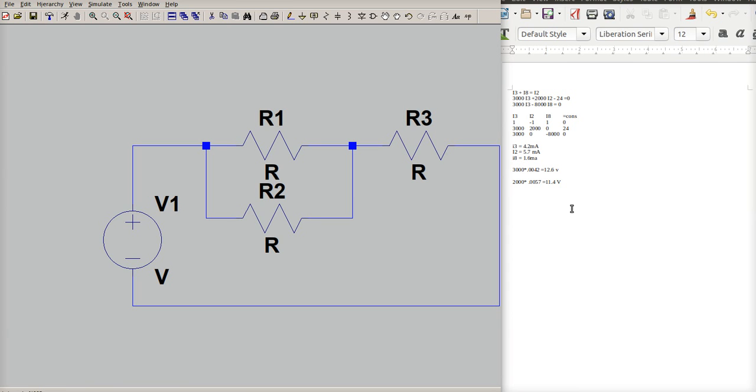Alright, I'm leaving these values here just so we can see how SPICE analysis compares with what we saw manually. The other thing that you have to have in circuit analysis using software is a ground. And a ground basically assigns a wire to 0 or node 0. I like to put them underneath the minus of my power supply. You can put a ground anywhere you want in the circuit, anywhere that makes sense to you, and even if it doesn't make sense to you, the software won't care, it will solve it. But I just made this wire from the minus side of my power supply all the way around to this resistor, wire 0. And so this is my reference. So any voltage measurements will be referenced to my 0 or my ground.